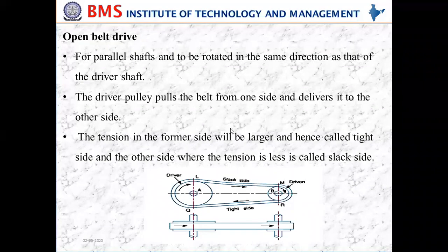And here we are discussing the flat belt. So when you look at this flat belt for parallel shafts, this is the shaft A, and then B, this is the shaft in the top view. So these are the two views he has drawn here, the front view and the top view. In the top view you can see the shaft is placed like this, and over the shaft we mount a driver pulley. And here is one more shaft. This is called the driving shaft, and this is called the driven shaft. And on the driven shaft, we have mounted a pulley called the driven pulley.